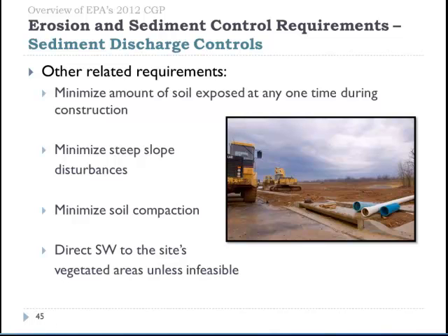Some of the other related requirements that affect the discharge of sediment and minimizing soil erosion is the requirement to minimize the amount of soil exposed at any one time. And here we don't specify a number that we're thinking about in terms of the maximum amount of acres that can be disturbed. It's a general requirement, but also permittees should keep in mind that any area that's opened up and isn't worked on for 14 or more days is affected by the stabilization requirements that I'll be talking about in a minute.